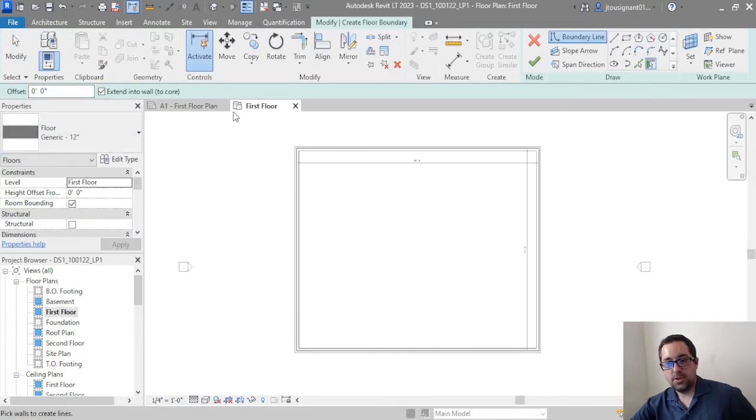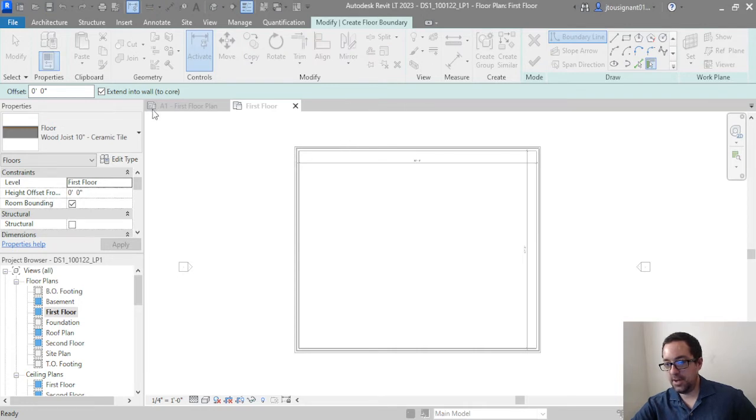So when you start the floor tool, by default, the type is going to be a generic one. As I mentioned last time, I don't prefer generic families. I prefer to work with one of the ones that has some type of system in it, because it's going to have numbers and values in it that are a little bit easier to work with, more accurate with combining to each other. I'll eventually get into the function layers at one point, either in floors or walls or roofs. Those are all three really good systems families to talk about with that.